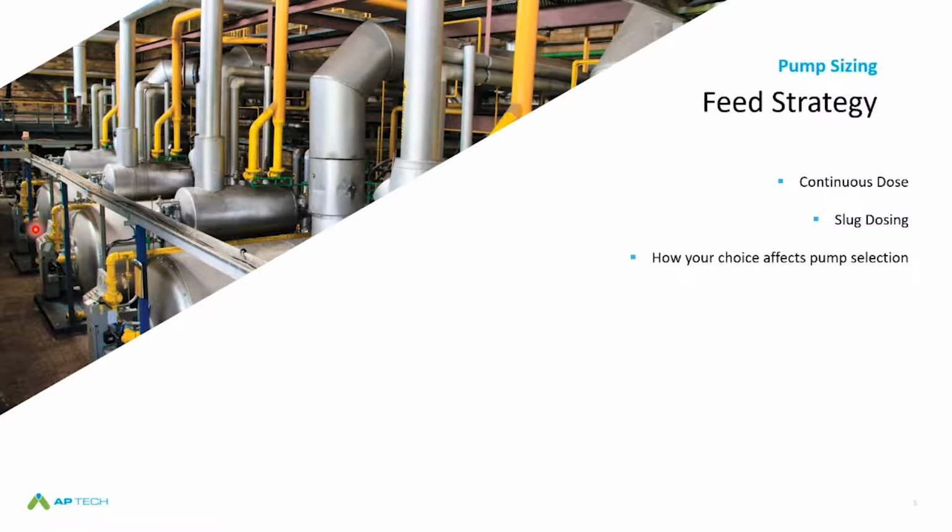That's typically what a continuous dose is, or a continuous dose could be just a low level dose where every 30 seconds you send 1 pulse, and you're just adding the chemistry because you just want a slight residual of whatever the chemistry is in that system. But on the continuous dose too, you could also have chemical pumps slaved to ORP. Using oxidizing biocides, that's what you're using ORP for, oxidation reduction potential.